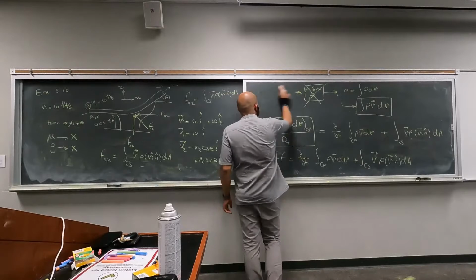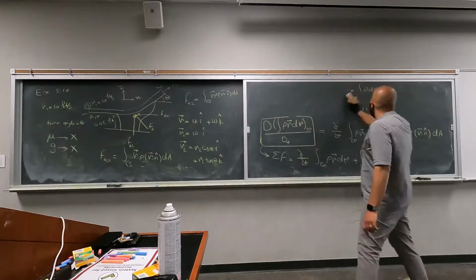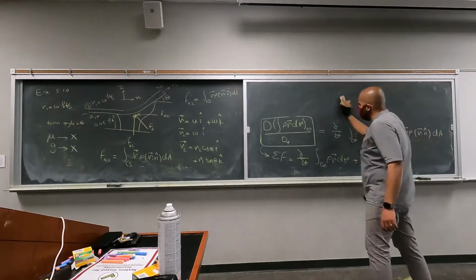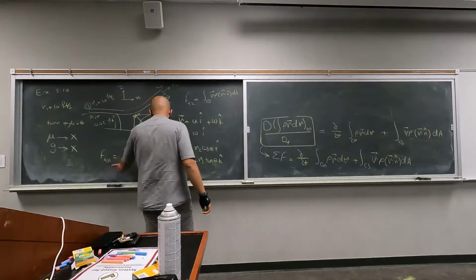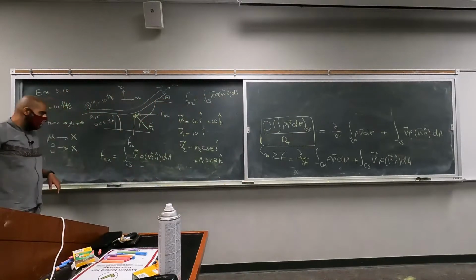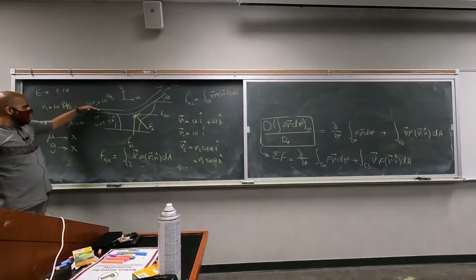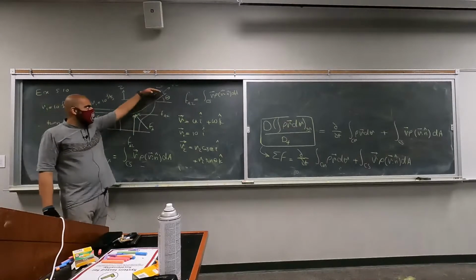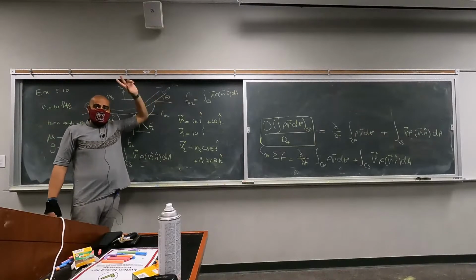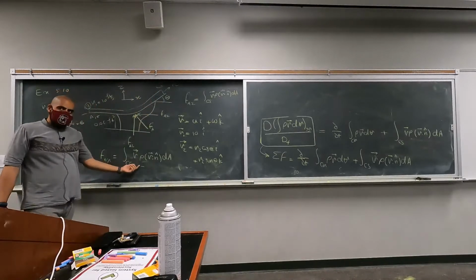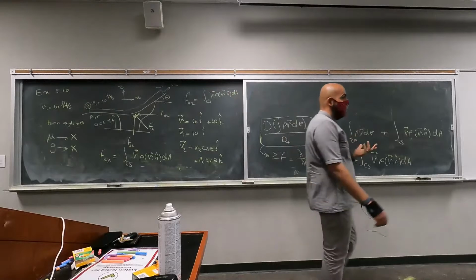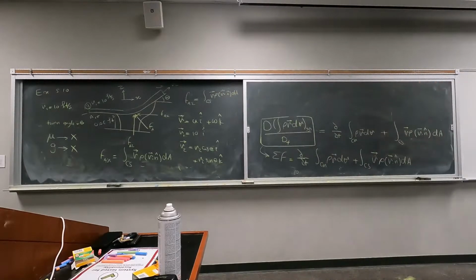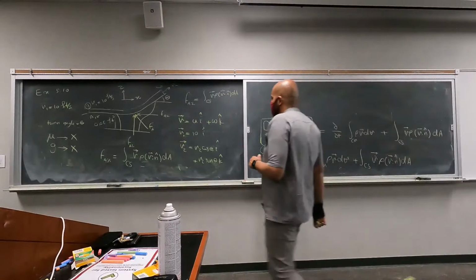So let's try to solve the problem in the x direction first. Fax is equal to this integral. In the x direction, flow is going in the x direction, and whatever is going out in the x direction, the linear momentum in those directions. We're going to assume density is constant, so we can take it out of the integral. We are also told that the velocity is just 10 feet per second, so it's uniformly distributed. We can take that out of the integral as well.